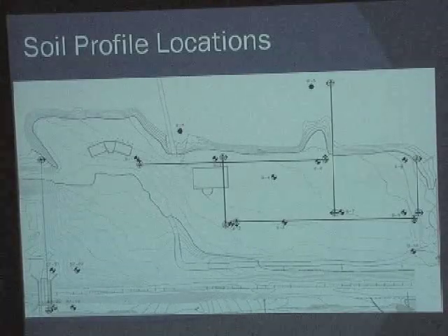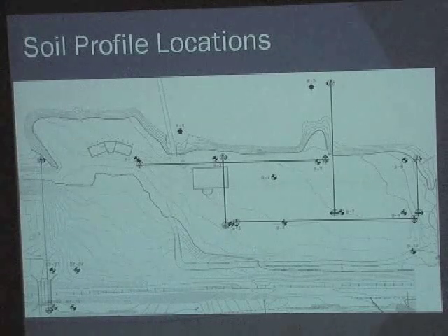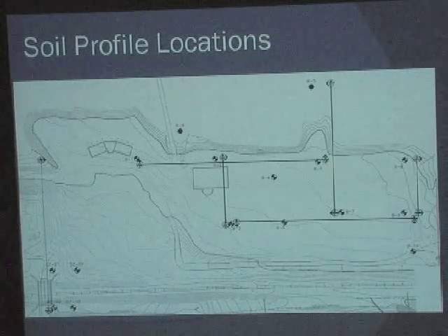Our first challenge with this site was to determine the soil underneath the major structures. Profiles A, B, and C were used to determine the soil underneath the restaurant, shops, and bridge. Under each structure is uncontrolled fill, sand, glacial till, and decomposed rock.